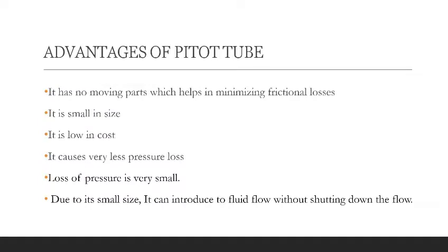And advantages of the Pitot tube. It has no moving parts, which helps in minimizing frictional losses. It is small in size and low in cost, and causes very little pressure loss. Due to its small size, it can be introduced to fluid flow without shutting down the flow.